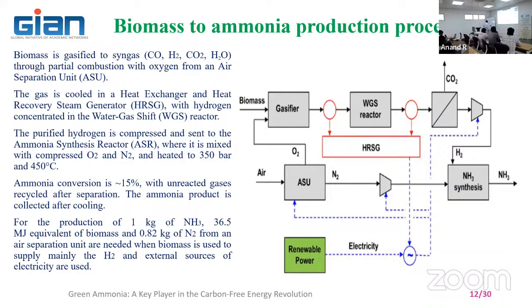It's an online system calorimeter. You can measure how much energy is going to be liberated when you burn a unit volume of the fluid. That is very important when we talk about gas. The unit is megajoule per cubic meter. If you want it in terms of megajoule per kg, you need to multiply by the density of the gas coming out, corresponding to the temperature leaving from the gas.